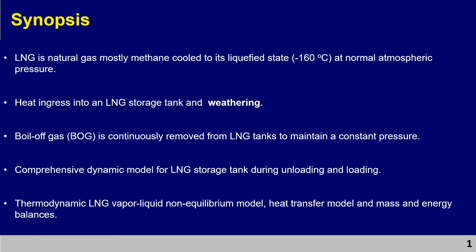It deals with LNG, which is natural gas, mostly methane, cooled to its liquefied state at normal atmospheric pressure. Regardless of how we insulate the storage tanks, you always have heat ingress into the LNG storage tanks, and this causes a phenomenon called weathering. Weathering is the preferential vaporization of methane and nitrogen in the tank, and this changes the thermodynamic properties of the remaining LNG in the tank.